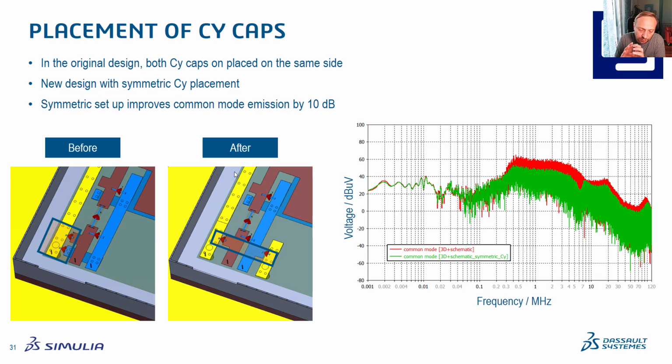The simulation is completely coupled inside CST Studio. You hit the button, it first calculates the 3D model, then hands over data to the circuit. Circuit simulation is running, handing the data back to 3D. That's all automated, all running after you have set up the model with one button press. And this allows you, instead of looking at RLC, to look at your geometry.